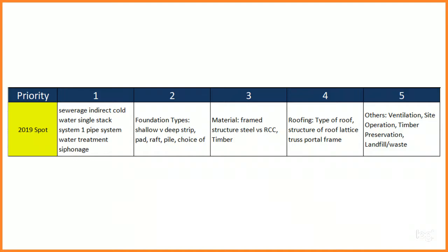Like in a factory, you use a certain type of portal roofing, for the reason that it can span a very wide area without support in the middle, because your factory is housing certain big machinery, so you cannot have a lot of poles and a lot of beam supports that would interfere with your machinery location.